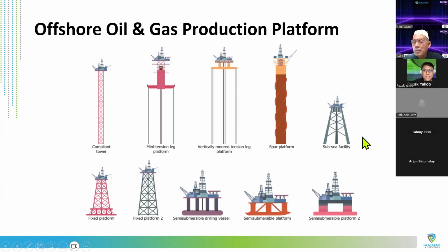This is normal subsea facilities. If you want to have facilities, then of course you have the platform, but facilities mean you have all your oil from the subsea produced to the platform. This is for shallow water depth, 200 meters, for example. And this is all the fixed structure, within 300, 500 meters more or less. If you have 500 meters water depth, then the structure is not going to be too much. Otherwise, you need a lot of steel if it's too deep. And that's why you convert back to your storage here, the tension cable, rather than using steel, using cable and float your facilities. So that's why it's all economics.